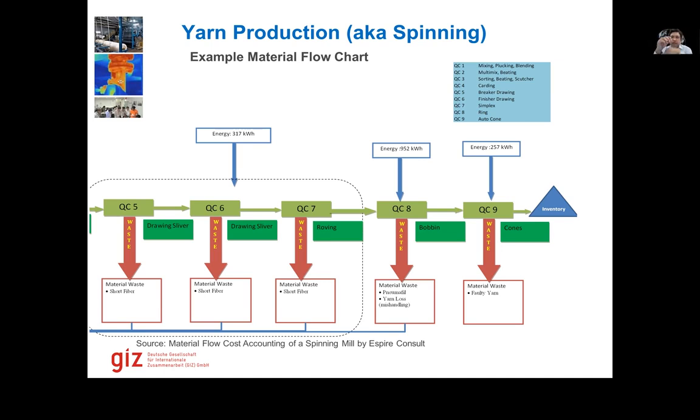How it is done is that we twist it, and based on the number of twists, the number of process steps varies. If we have only a single twist, we might have only one step of machines. But if we have a process called doubling, where we have a double twist, these are thicker and stronger yarns, used for example in areas where we need more strength in the yarn.